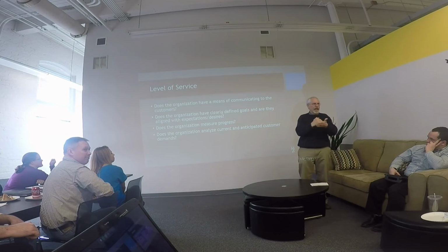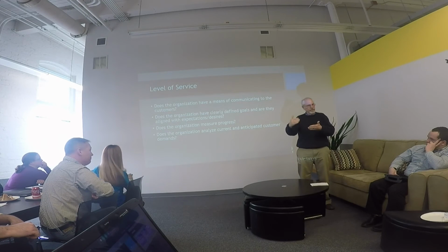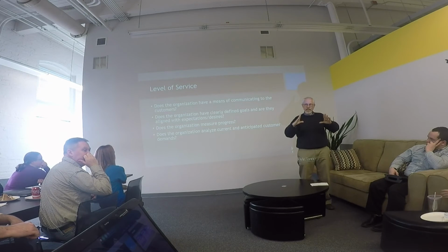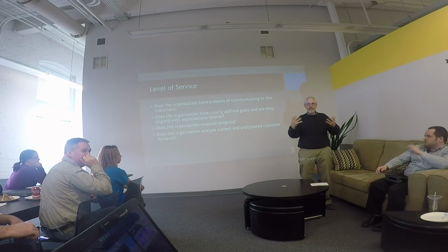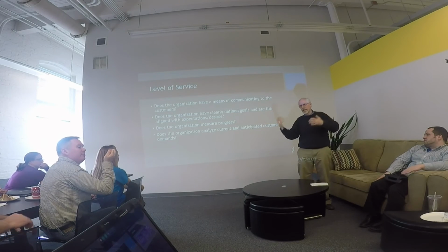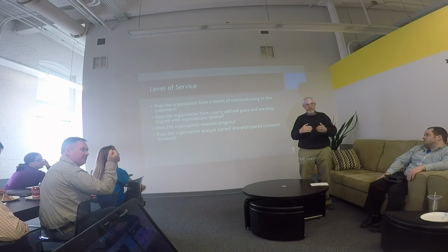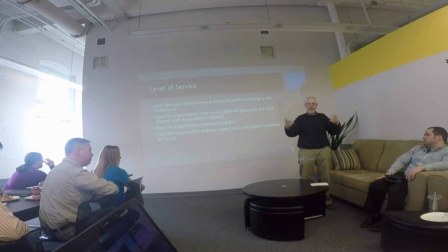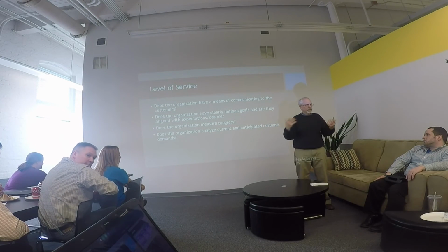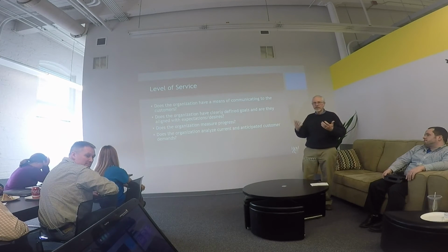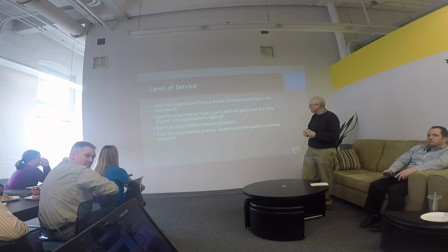Or you will not block that road from two-way traffic for a certain amount of time. Once that level of service is in the spec and the businesses know it and everybody knows it, there are fewer complaints that the contractor's not doing this. If he's meeting that level of service and those stores know what it is, it becomes a much more transparent process. So that's again how engineers could utilize level of service.